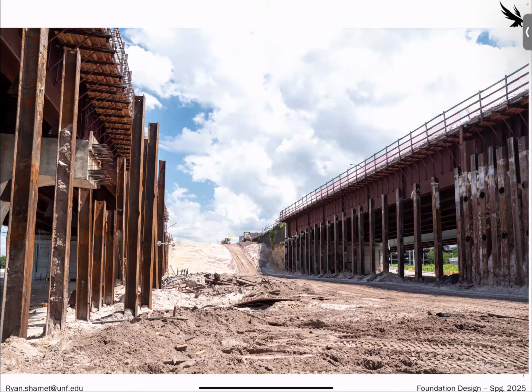But you're designing these piles. These are called soldier pile walls. You've probably seen them. They're normally stacked with wood in between each thing, and they're actually a retaining structure. And they use them as a temporary, like if they need to move traffic over to one side and build a temporary embankment. And since they're vibrated in, they can be vibrated out, and they're very easily switched back and forth. So not only might you be designing permanent foundations, you can also use this to design temporary foundations. And obviously the type of foundation, whether it be a steel H pile, would be more suited for one or the other.